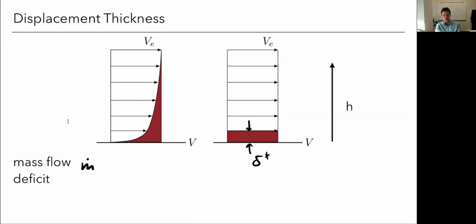All of those things are all constant. And I'm integrating from 0 to h just for convenience. So I start from here to there. But now I've got to subtract out this part that doesn't contribute, right? That's my wall. And so that's going to be, I could write this also as an integral, but I'm going to skip that because, again, this just makes the derivation easier. Okay, so like that. All right, so this first term, I could have written as rho edge v edge times h, right? Or this whole thing is just rho edge v edge times h minus delta, this height here, okay? But leaving it like this will make things simpler.